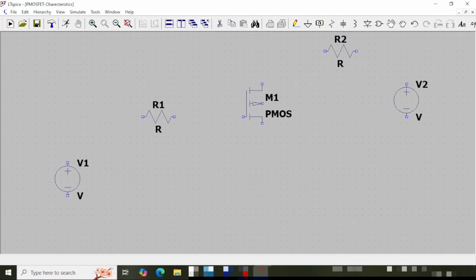Now one thing here, you can see the voltages are there. While interconnecting, I have to flip the plus and minus. For that, I'll hit the M key from the keyboard to select and move. Now I'll select Ctrl plus R to rotate it. So it has rotated clockwise 90 degrees. I'll again click Ctrl plus R to rotate it. So now you can see the voltage plus and minus terminals are flipped vertically. Now I'll click and place it.